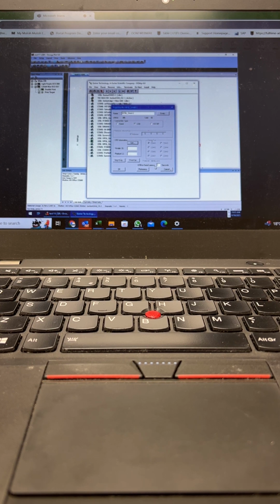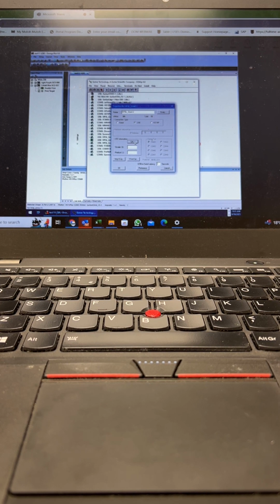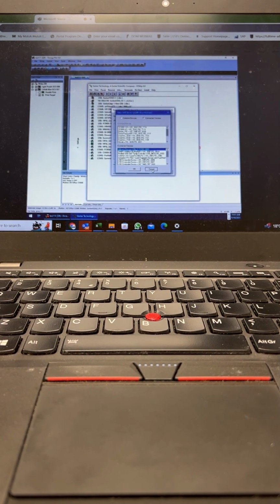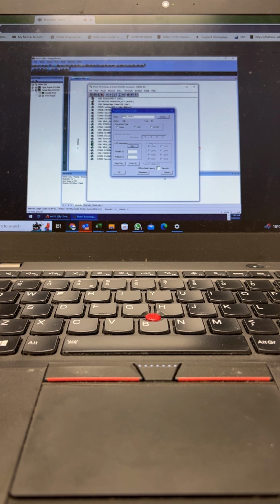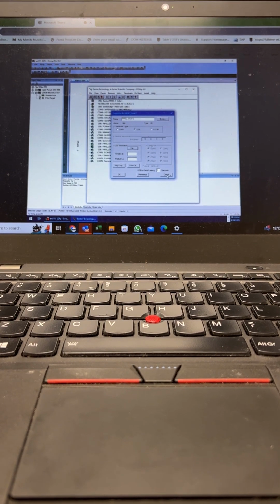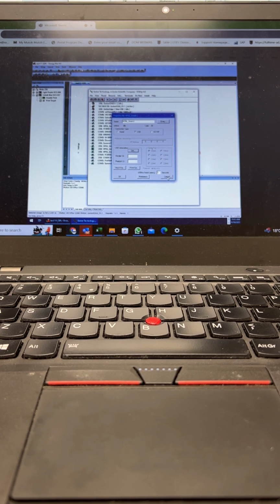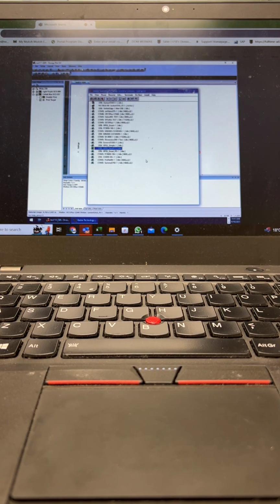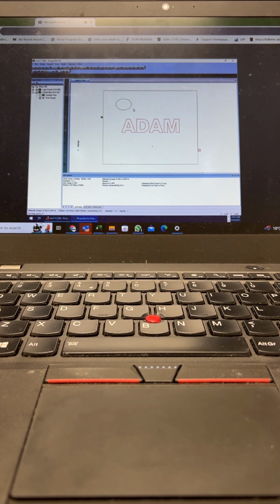If you change the plotter, do service on the plotter, or replace the main board in the plotter, that VID information may change. So if they get service on their equipment, they may need to go into this and change that information to output again. Generally not something you have to deal with during install, but if the customer had work done and it worked before, now it doesn't work with the new software. Oh, and I just had the plotter's main board replaced. Okay. The story always thickens. So that's the Gerber GQ Manager, Gerber Plot Software.